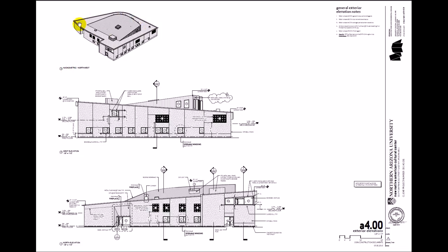Okay, this building has curves and it has sloped roofs. There's that little elevator pop up where we're seeing punched windows. So I now have traversed the whole kind of set of drawings, and I have a feel for what's going on. It looked like back in this area by the elevator we had a little mezzanine. Otherwise, it's for the most part a single-story building. And that helps me understand the structure. So let's jump back to the structural drawings and take a little closer look.